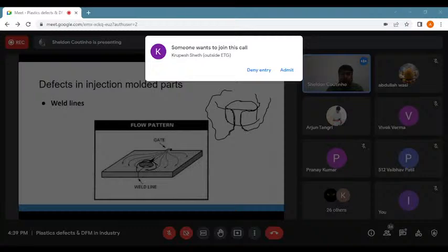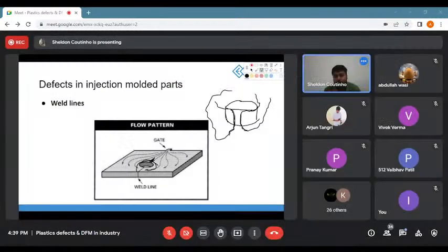Exactly. So ये दो अलग layers जब भी form होते हैं, because the outermost, as I told you, ये real world है, so you will have cooling, right? So since this is the outermost layer, it will start solidifying, and the temperature, as just now Arjun pointed out, will not be enough to create a homogenized structure over here. So वो join तो हो जाएगा, चलो, it will stick, but it will yet have that line, because it has cooled at different rates and it is coming close, that's why it is going to form this line.